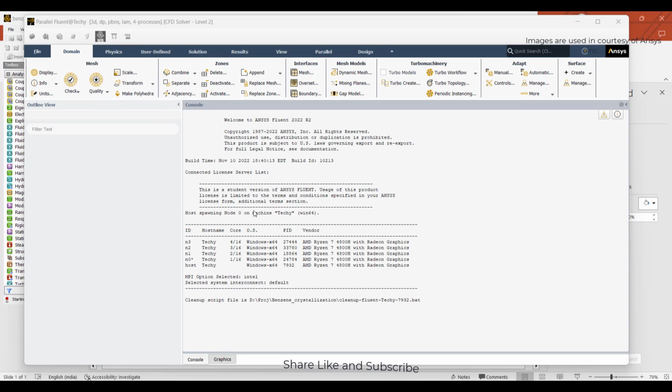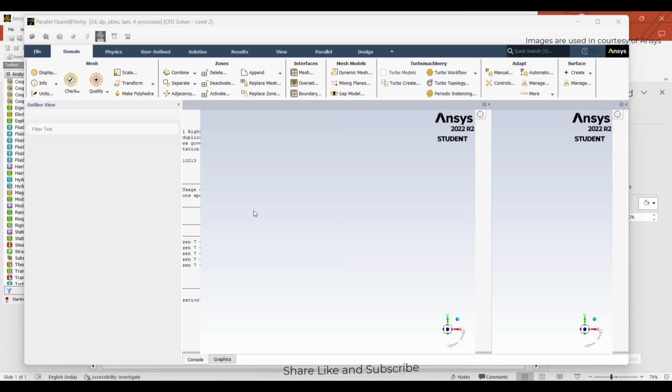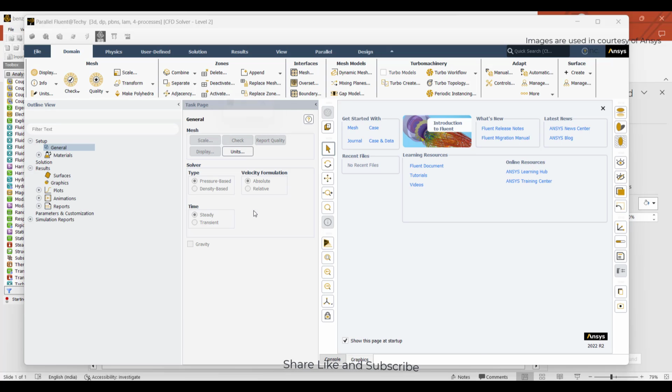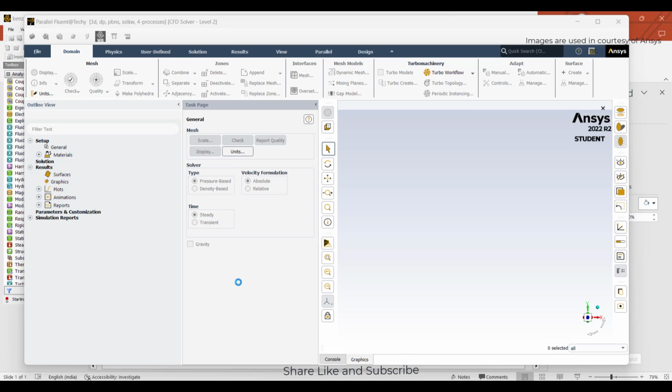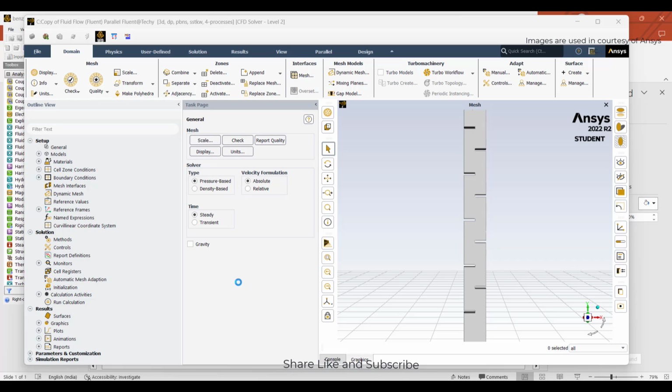Importantly, it should reach the sublimation pressure in order to have the condensation or desublimation from vapor to particles. It will check for each cell whether the cell is meeting that criteria. Then the particles will be formed, and the particles will grow according to the size I have given, and the initial particle size will be the critical radius.